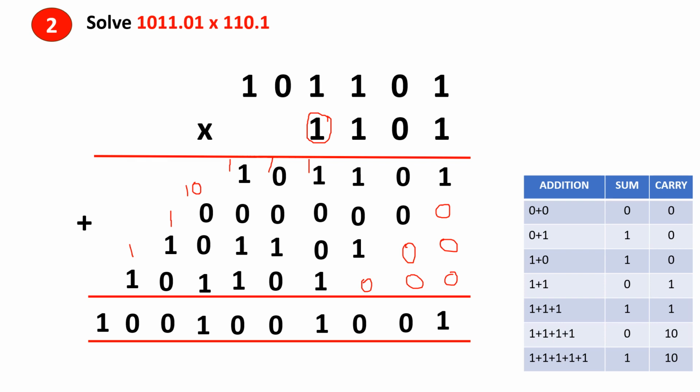So now let us verify this with the decimal multiplication. Before that, let's put the binary point. So here the binary point comes here. For this it is here. So in the fraction part there are 2 bits here, and there are 2 bits here. Here in the fraction part there is only 1 bit. So altogether 3. In the answer, the fraction part should have 3 bits. So you can keep the point here.